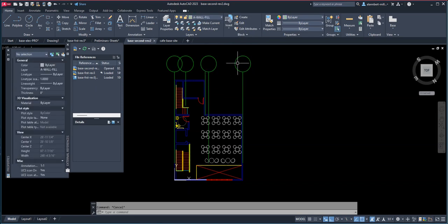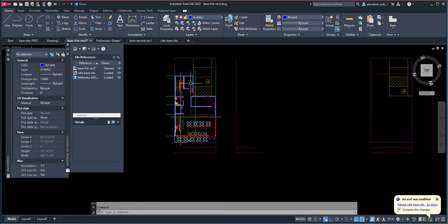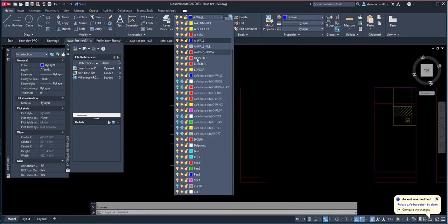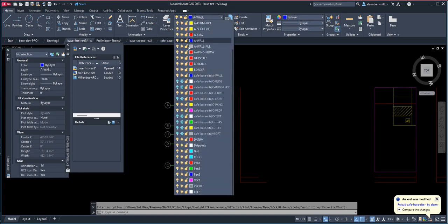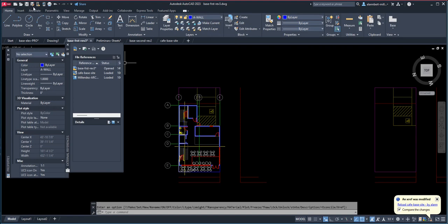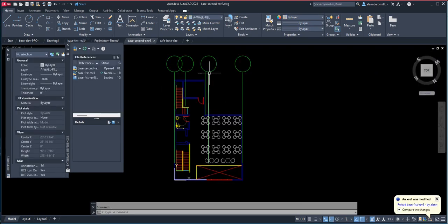So I know that on the first floor we put the bubble sheets on a layer called viewport, so it doesn't print, right? If I put that on, I can see this back here. So save that. We can do the same thing. We can go to the second floor rev and then erase all of this.